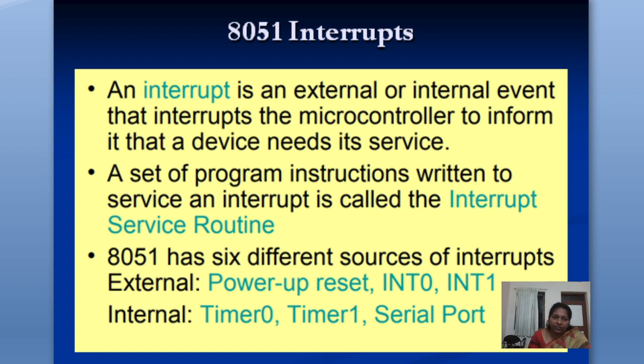So in 8051, what do we have? We have different types of interrupts. There are 6 different types. There are software interrupts, hardware interrupts, and all are vectored interrupts. Power on reset is always taken as an interrupt. You can consider it, or you need not mention it. Then you have INT0, INT1, which are hardware or external interrupts. External means some signal comes to a particular pin and